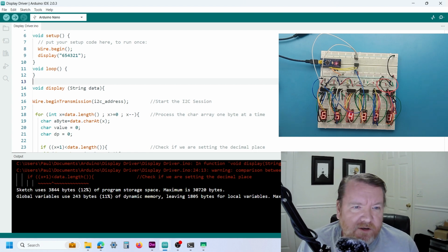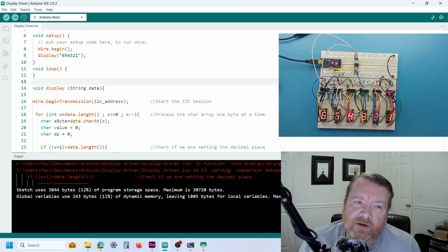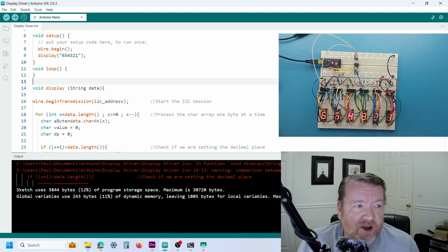And if I wanted to have multiple of these boards connected, I would need some way of changing the I2C address. So my plan is to put in some registers basically for the I2C, which we can set through the I2C bus to enable us to programmatically change the address. So I'm going to do that in the next video.